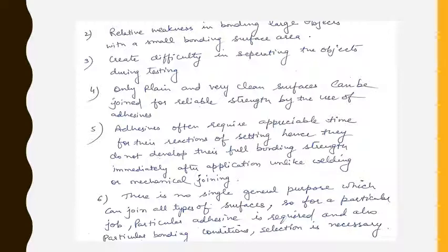Adhesives often require appreciable time for their setting reactions, hence they do not develop their full bonding strength immediately after application, unlike welding or mechanical joining. So you cannot say that by the use of the adhesive, it immediately goes for binding. It requires sufficient time for binding. In some applications like welding and joining, you have the effect immediately. When you do such a mechanical process, the binding takes place immediately, but that can't happen with adhesive.